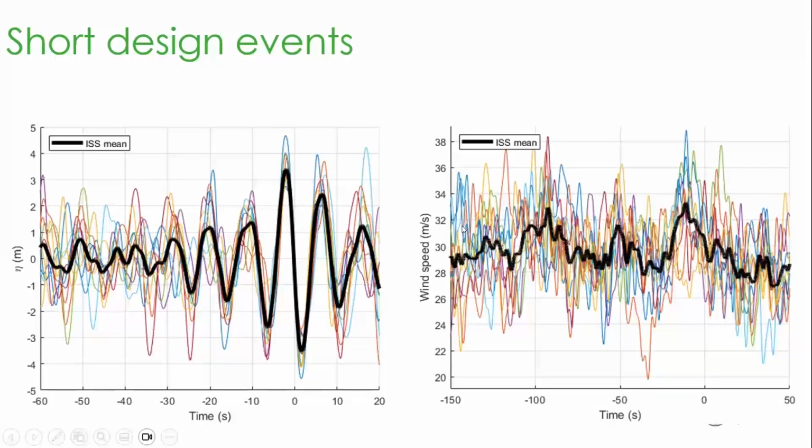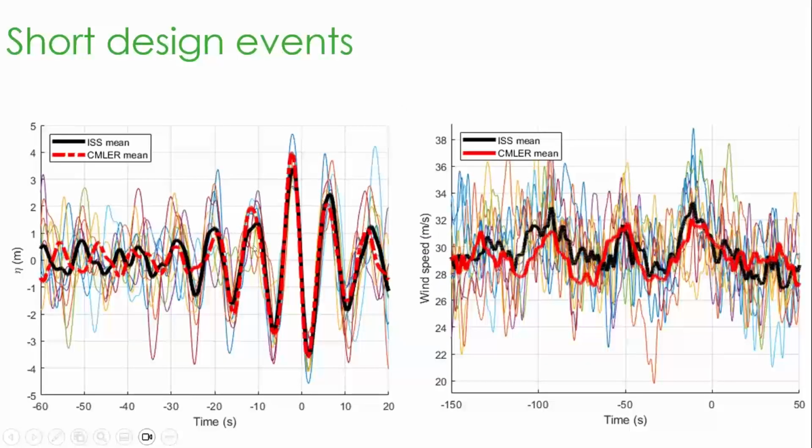So here we have the 10 different background cases given by the background lines, and then the average wind profile given by the solid line. After that, we've taken the RAOs for the device and produced these response condition profiles. And when we overlay them, you can see that they match well with the empirical profiles. So this is an indication that it's working as we expect. So here, this red profile is the average of the 20 constrained cases.